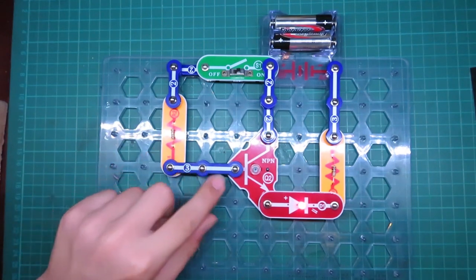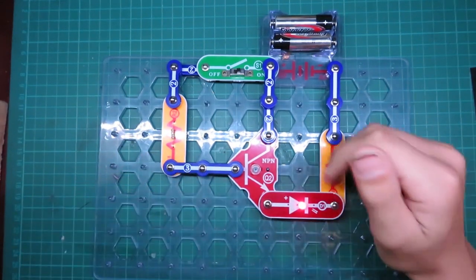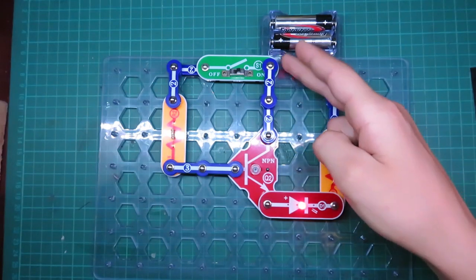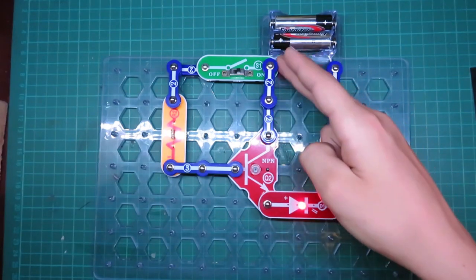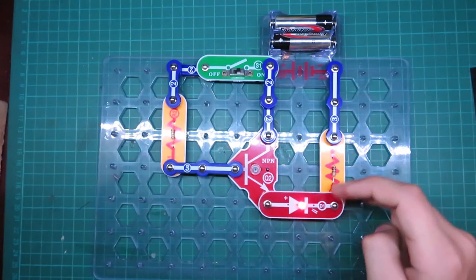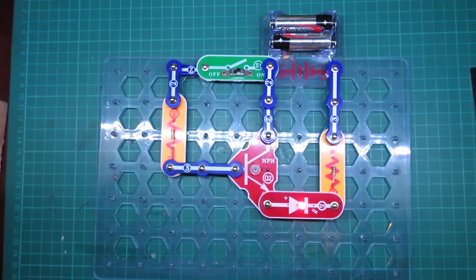And that current goes into the base, and so now that the transistor is turned on, current can flow from the positive to positive through the collector to the emitter, and through the LED back to the negative. So that's how you use a transistor as a switch.